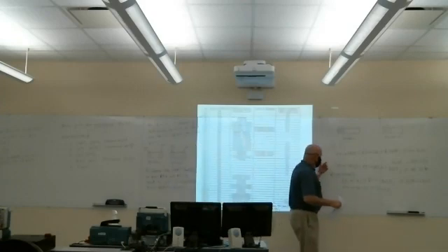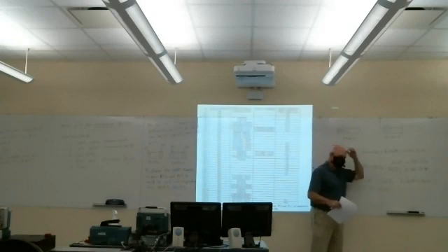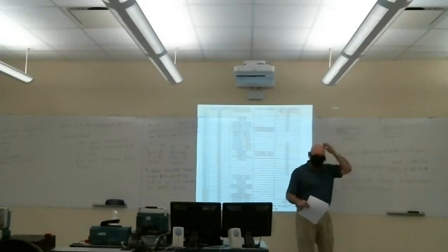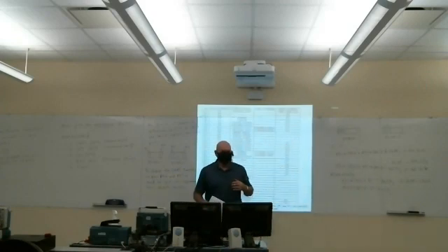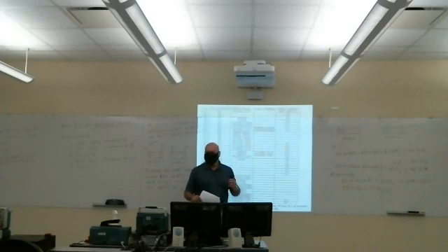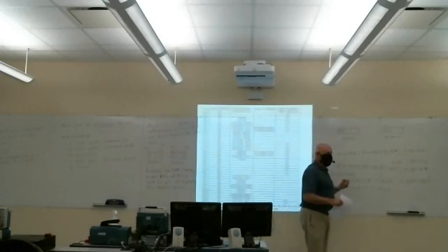Now, if I needed to clear the bits in the selection 0 register, I would AND with, again, the not here. Or if I wanted to set them, again, OR with the value I get from those 2 bits. Any questions about that? That tilde sign means a binary not.